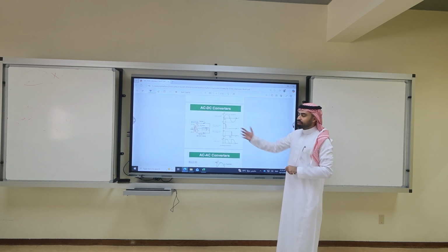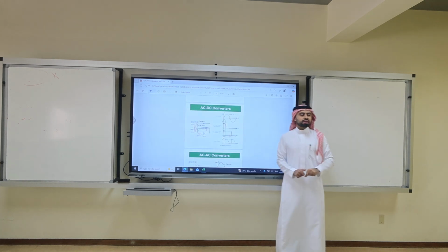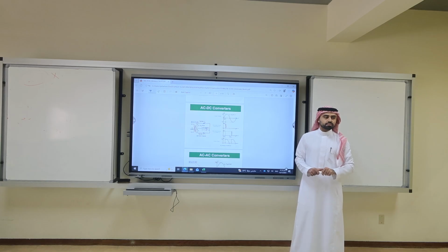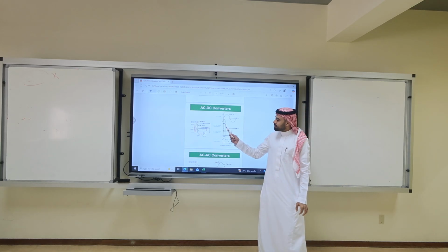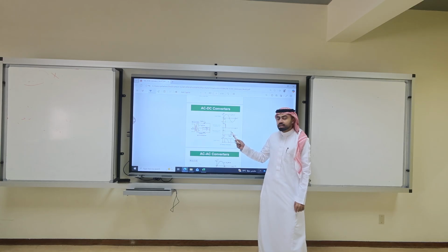Then we talked about a thyristor. What is a thyristor? A diode with a gate. So it will not rectify until the pulse is sent. If I send the pulse, I start rectification. And once it turns off, it will remain off until I send the other pulse. So the negative cycle will be rectified.